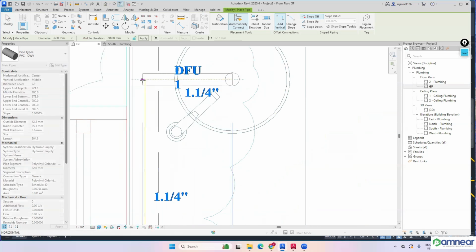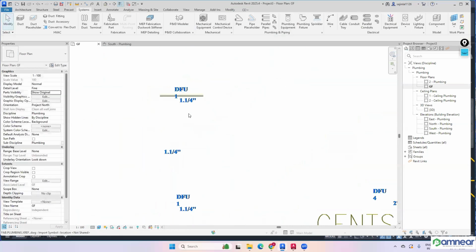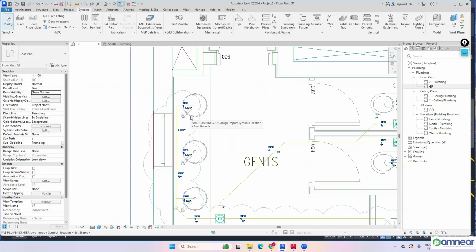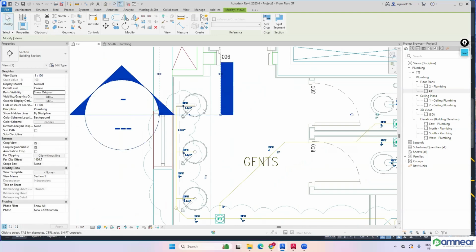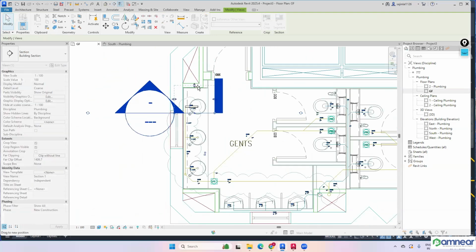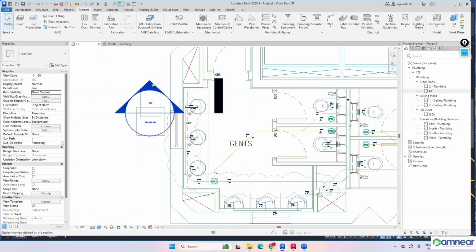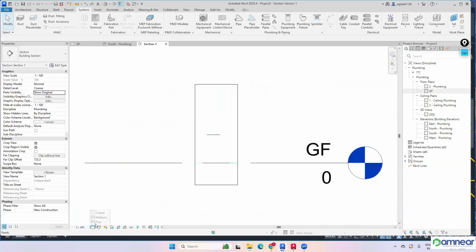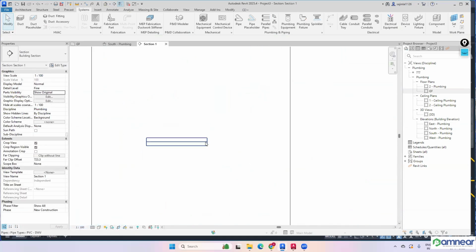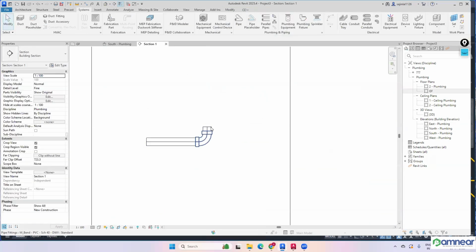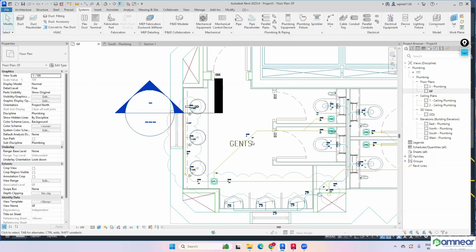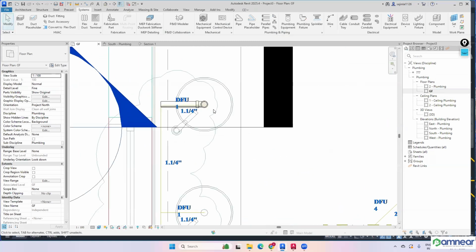Okay, let's say 700. Then make it fine and realistic. So I'll be connecting up to there. And I'm just making a section because, as you know, sometimes we'll be having a bottle trap there, or a P trap or U trap can come there. So that's why this connection is coming from the wash basin. I'm just making an elbow upside so that I can witness better when I'm converting into 3D.